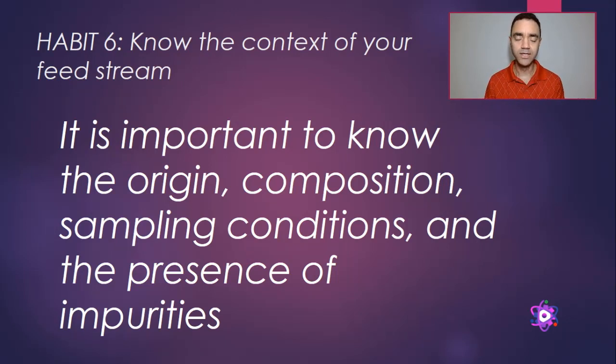Eventually, I will need to know the pressure and the temperature to make sure that the quantity of water that I can have in my stream is correct. Because if I consider a quantity of water or moisture in my feed stream too low for my process, when I design my system and I start running that, I will not achieve the performance because my equipment or my process was undersized.